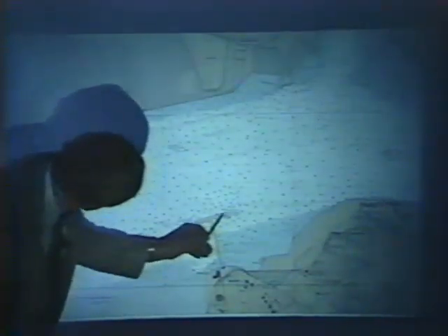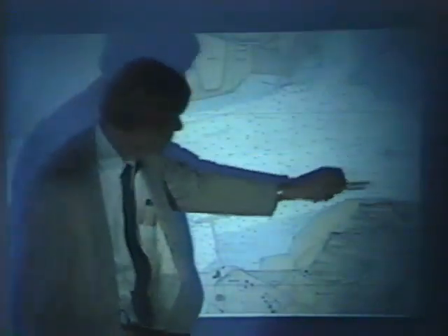Now, the currents here are sufficient to make the strait really deep. It's 100 feet deep right about here, for example. And the currents out here are very strong also. So you'd expect a wharf placed parallel to the currents like that wouldn't have much of a dredging problem. Shouldn't. The currents are really high. The bottom is mostly sand, and it really shouldn't have much of a dredging problem. But they have to dredge it every other year. They have to dredge around. I'll explain why. There's a second one here that you can hardly see on the picture.